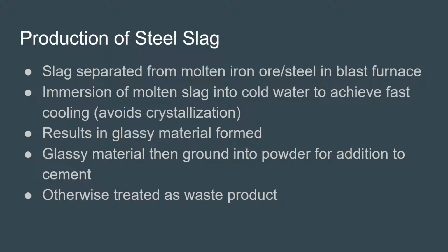Steel is manufactured in a process comprised of several phases. These phases involve the reduction of iron ore into pig iron, followed by the refinement of the iron into steel. It is then later formed into different shapes and compositions for distribution. During the first steps, iron ore exists in its molten phase at about 1500 degrees Celsius within a blast furnace.